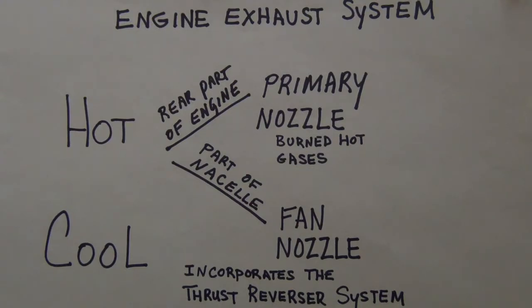You have an inner and an outer, so that inner outer, I'm talking about concentric, like a ring. That's your inner cowl, and then of course you have your outer one that's surrounding the inner one. Your actuators are also part of all of that, and of course the piping, and then also your stow switch, also your deploy switch. All right, so that gives you an idea of the components and the function of the engine exhaust system.